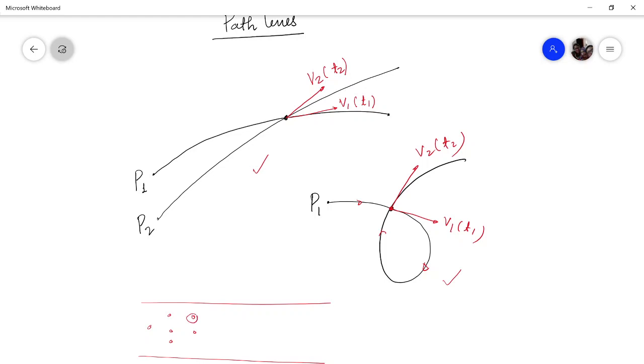If I focus on this particular particle, due to the motion of the fluid at this location, the particle will move in the pipe. This is the path of that neutrally buoyant particle, and it helps us understand the flow behavior. In lab coordinates you cannot generate streamlines, because they are instantaneous and mathematical, whereas you can generate path lines with the help of these neutrally buoyant tracer particles.